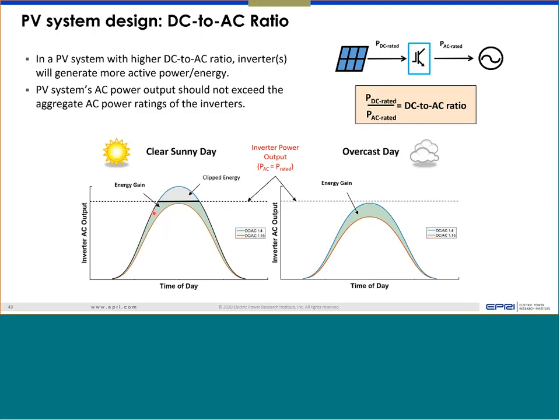And of course, there is degradation. Maybe if you're familiar with that, year by year panels get degraded by 0.5% or 1/4%. So even if it's 100 kilowatt today, 5 years later, it will not be 100 kilowatt anymore. Temperature is another factor. In a lot of cases, DC generation depends on the temperature. Like if you're in Arizona, your high temperature will reduce the power production from the panel. So a lot of factors go into those decisions.